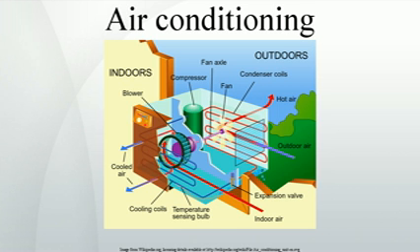Heat pumps. Heat pump is a term for a type of air conditioner in which the refrigeration cycle can be reversed, producing heating instead of cooling in the indoor environment. They are also commonly referred to, and marketed as, a reverse cycle air conditioner. Using an air conditioner in this way to produce heat is significantly more energy efficient than electric resistance heating.